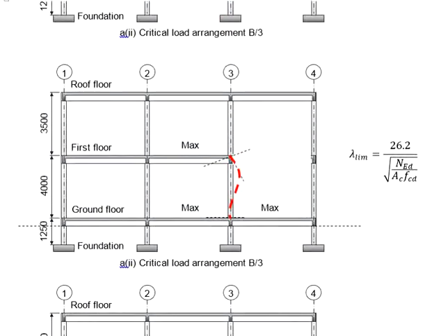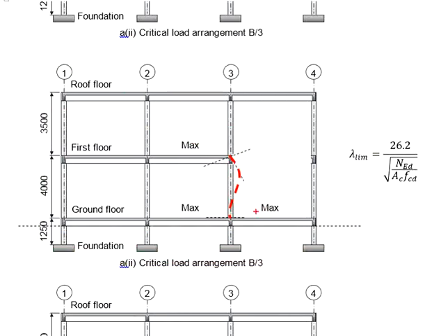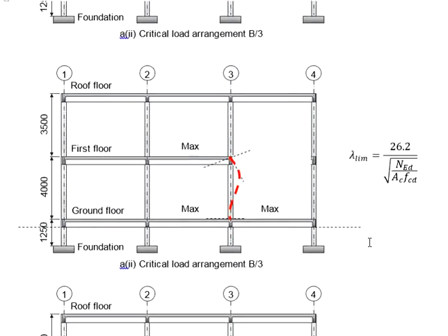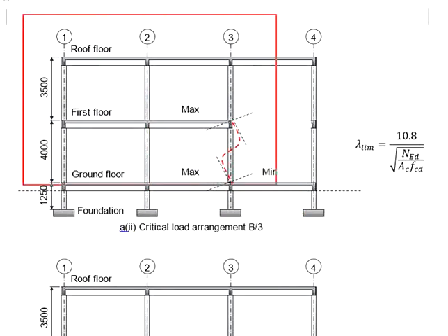We have another possible setup just for the sake of demonstration. Let's say now both sides are of maximum load, and when the spans here and here are the same, the fixed end moments generated by both beams shall cancel out each other, ultimately leading to zero moment here. I guess by now you should be able to determine which equations to be used in accordance with the load setup. Let us first start with this setup.